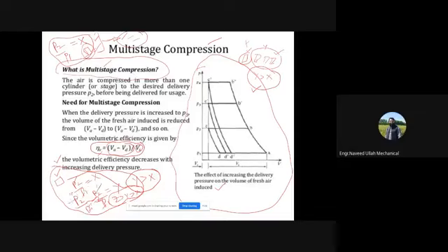So if you see here in this first case, this is basically your, you see, VA is the induced volume, this is your VD, this is your VA, and we will be having VA minus VD, that is here the induced volume, swept volume is the same, let's say. Now, this is actually compression and then it is delivery, and this one is expansion for this first case.